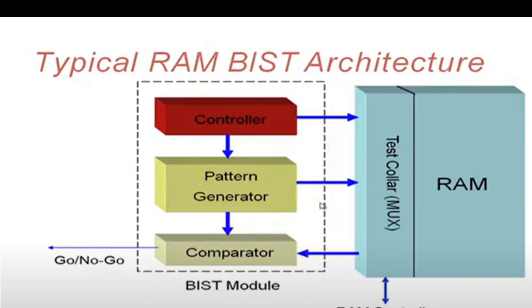So, in a typical RAM-based architecture, we generate the pattern and apply it to the RAM cell. The responses we obtain are compared, and we give a go or no go result, whether it's faulty or fault free. And we have a control circuit.